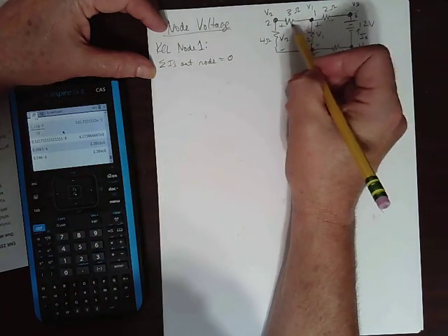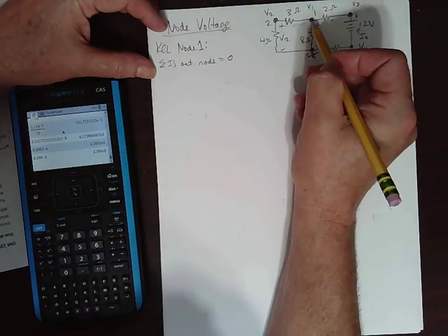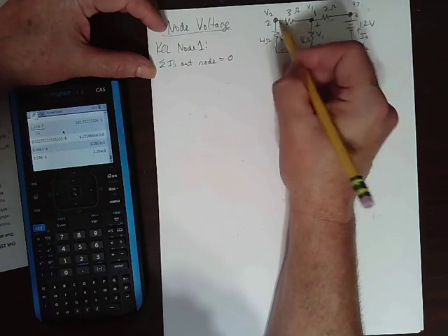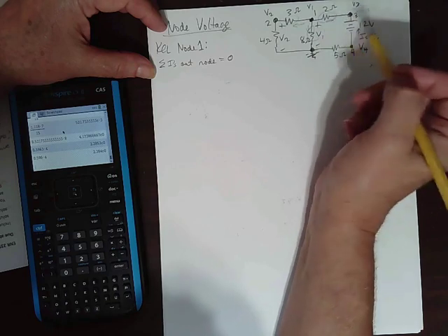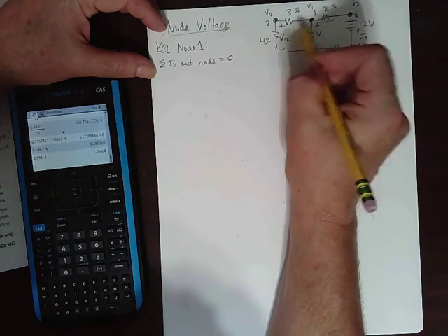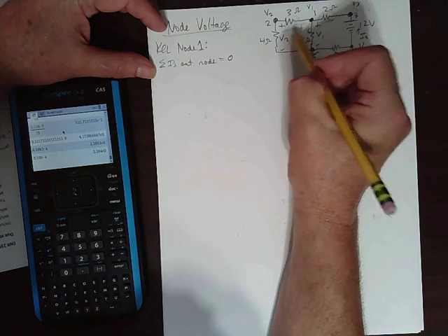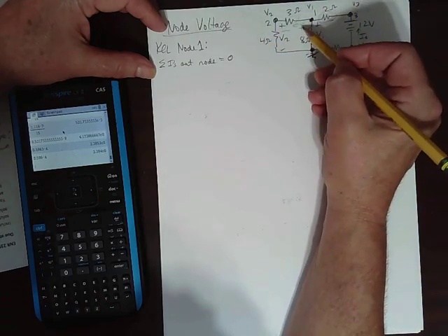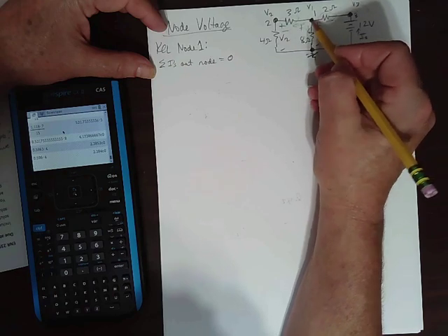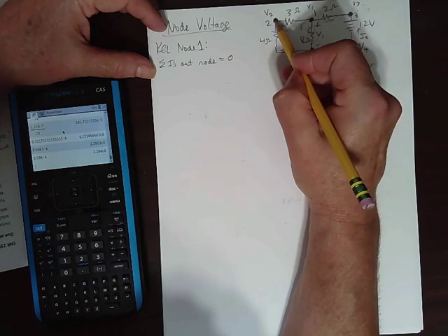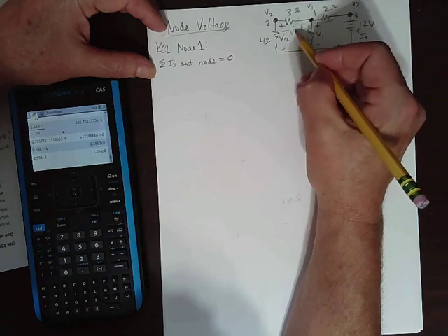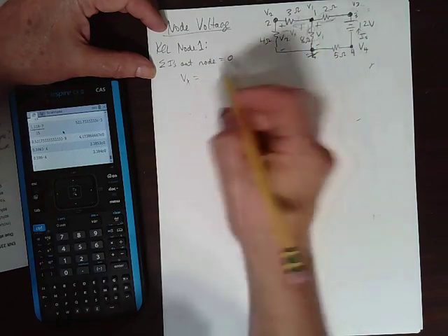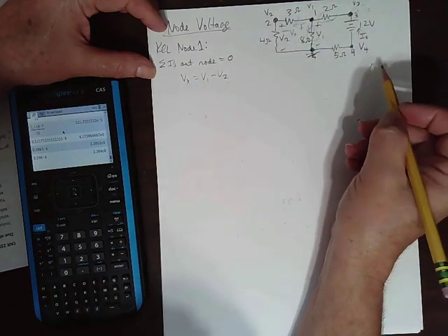So what is the current going this way? We're not going to give it a name, but we know that V equals IR, so I equals V over R, for this resistor. Since it's a nice resistor, it's easy to do the equations. We want the voltage plus here, minus here, because the current's going that way. We want current out of the node, so the current going that way means plus voltage here, minus voltage here. It means we want the high side here, the low side here. So the voltage, let's call it Vx for a minute. Vx is going to be V1 minus V2. That's just how it always works.